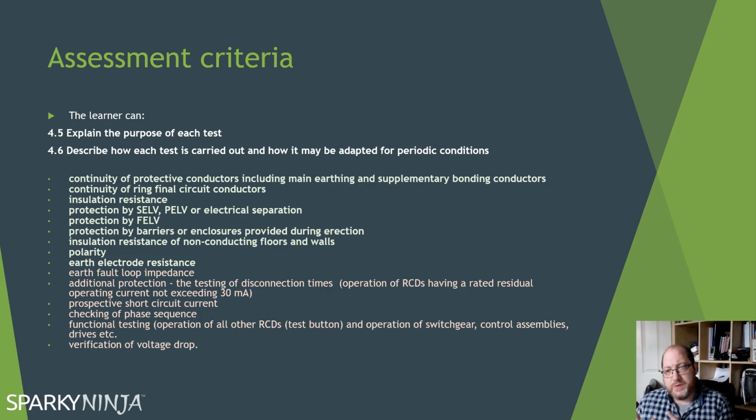So with periodics, we need to verify if any upgrade in distribution or introduction of larger parallels or anything like that has happened and subsequent switchgear has not been considered for selection.